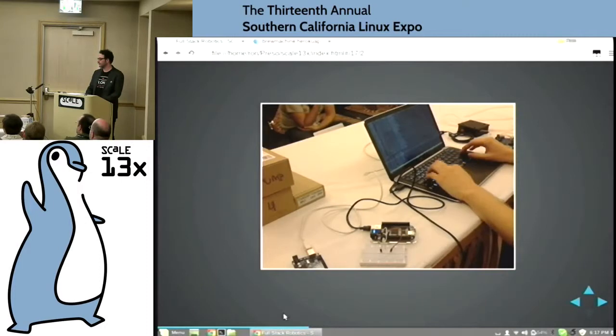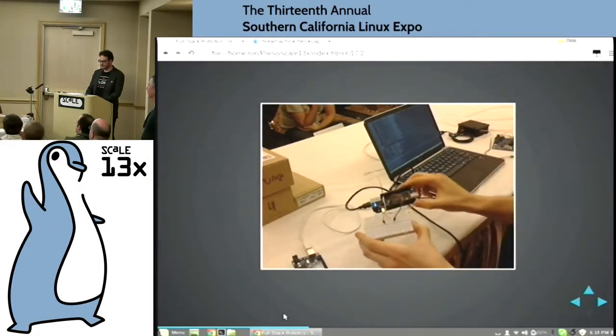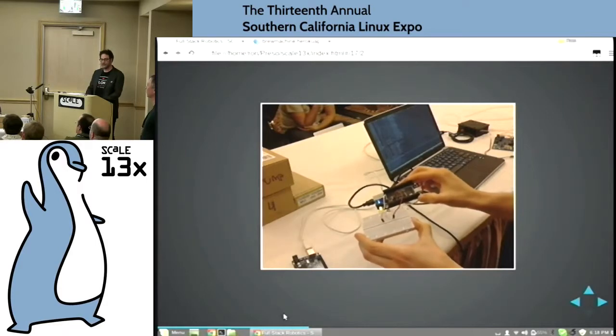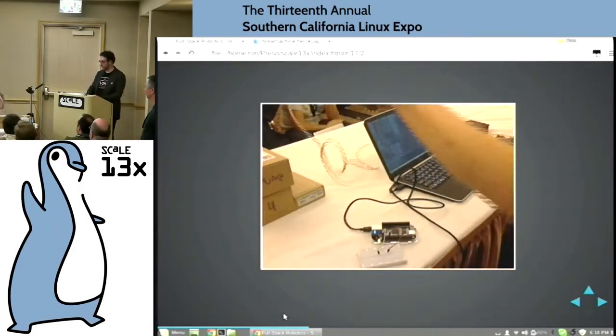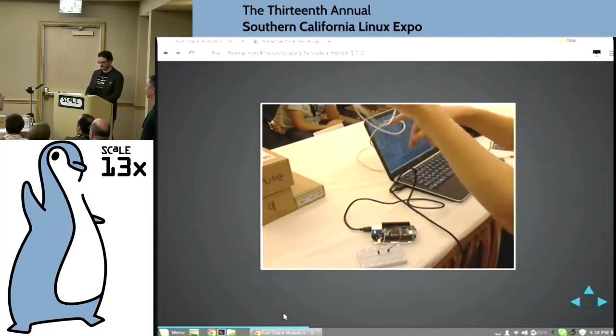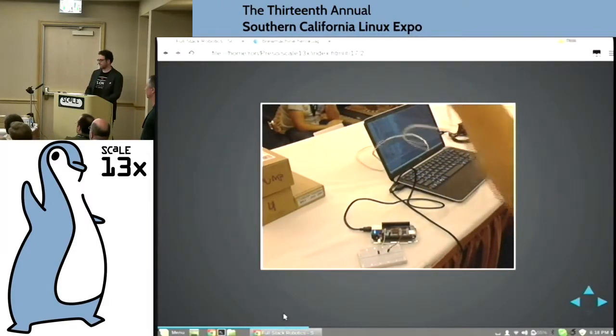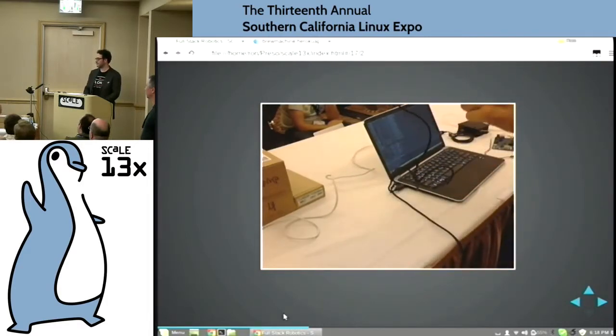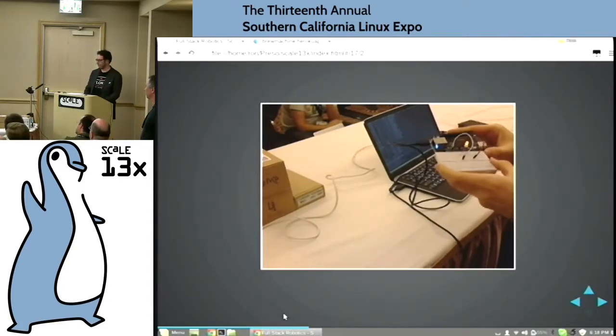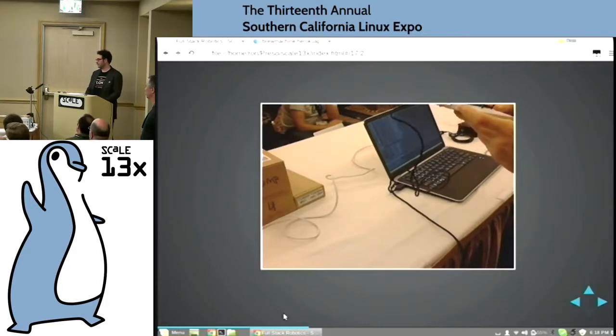program on the BeagleBone Black itself. And it blinks. Now look how fast that was. For the Arduino, this was plugged into my laptop using a remote serial interface. For this example, the code is actually running on the board itself. So you're programming the firmware for your connected device on the device itself. This does not need any outside system to coordinate or control it. It's completely autonomous.